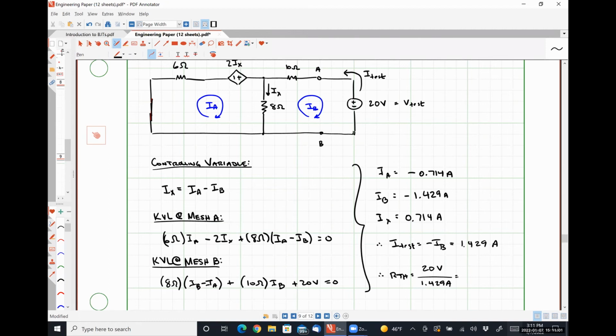So that's going to be 20 divided by 10/7, which is exactly 14 ohms, which is the result that we got taking the Thevenin voltage and dividing it by the Norton current that we calculated several minutes ago. Okay. So our test voltage method obviously returns the correct answer.